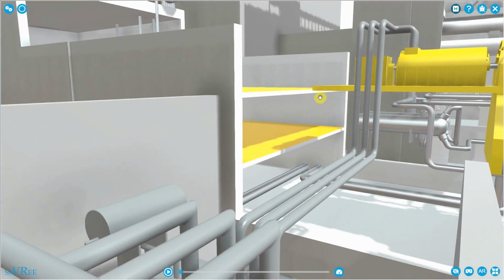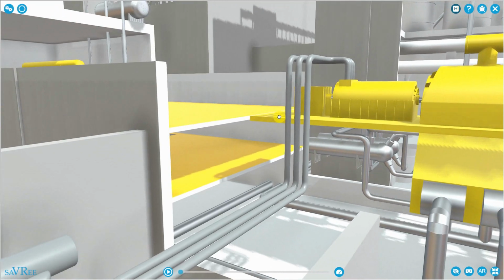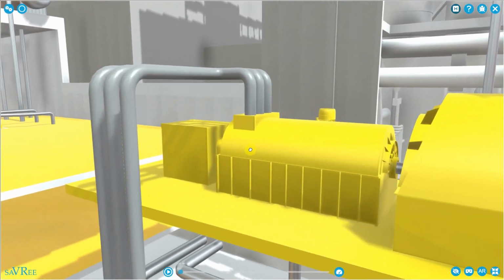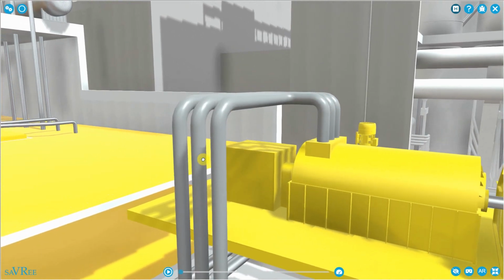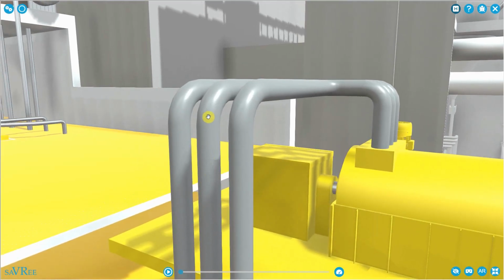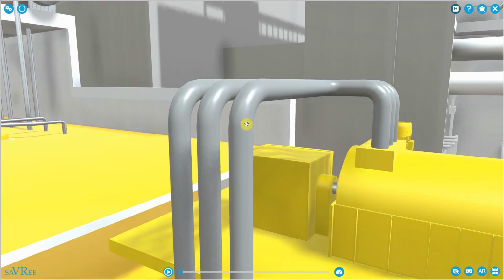This must be quite a modern power plant. The reason I say that is because these connections coming out are not the actual connections from the generator. The connections from the generator will just be copper bars, maybe even aluminium, but whatever the material is, it will be a very good electrical conductor. Those bars are going to be sitting within these pipes.